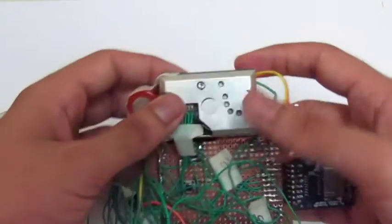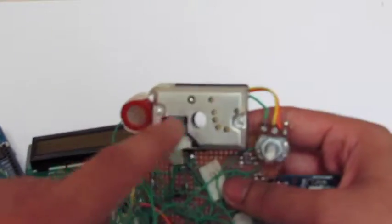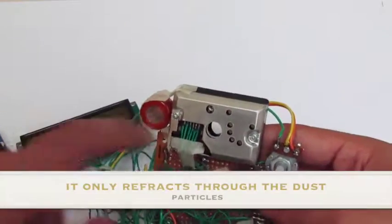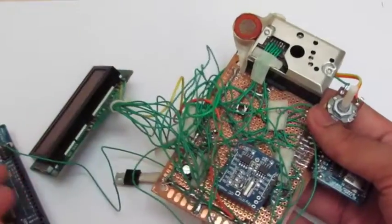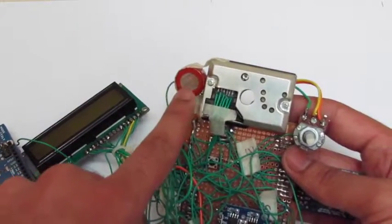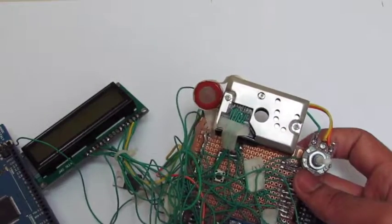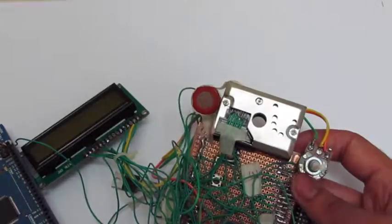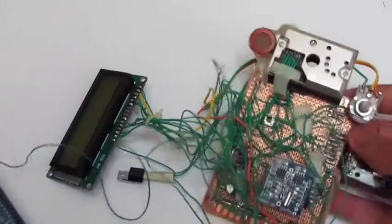In order to receive the data, I have a Sharp dust particle counting sensor. The dust particles go through this and the LED light inside diffracts and refracts when it interacts with dust particles, and that is the data which is given to our Arduino board via the serial. And we have a carbon monoxide MQ7 sensor, which has an inbuilt heater, and the change in this temperature affects the plate inside, which reacts to the carbon monoxide in the air, and we get all of that data through the analog pin on the Arduino.